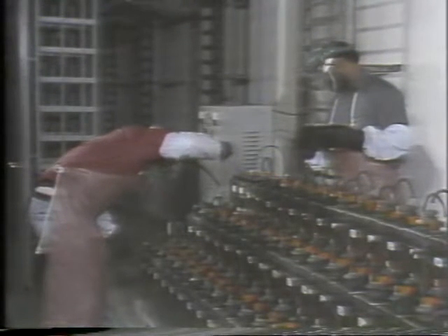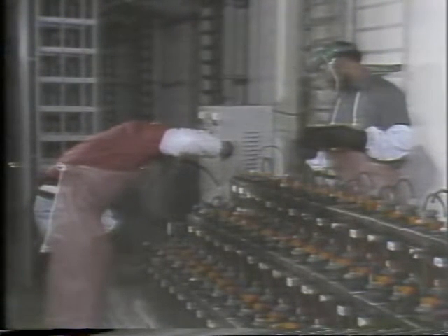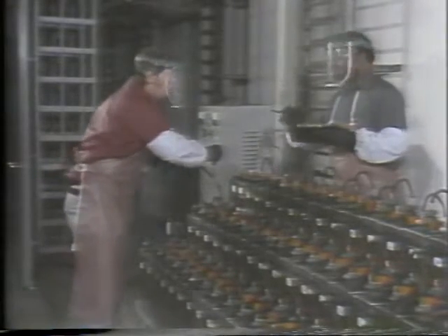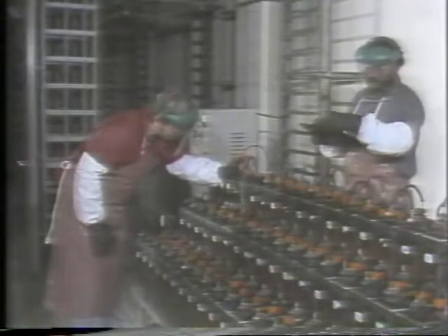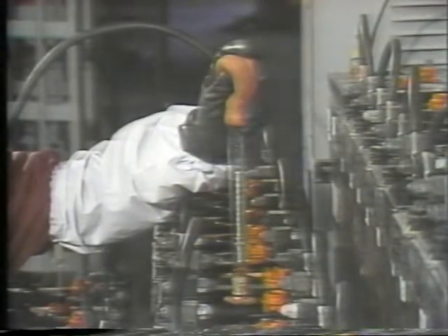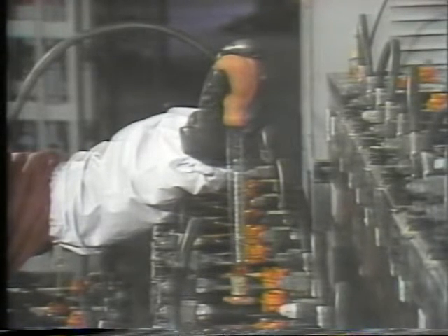Checking specific gravity with a hydrometer is a normal part of periodic battery testing. Each cell must be tested individually, and the reading is recorded so that it can be compared with previous results. To make a specific gravity check, squeeze the bulb, then place the hydrometer's nozzle in the cell. Release the bulb so that electrolyte is drawn into the barrel.